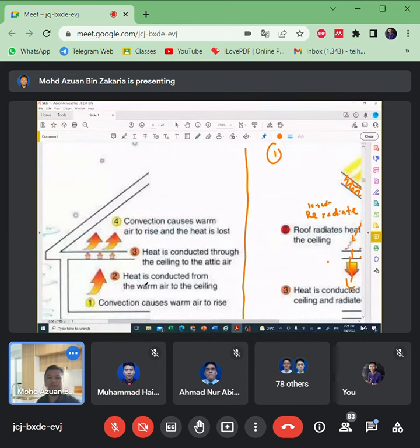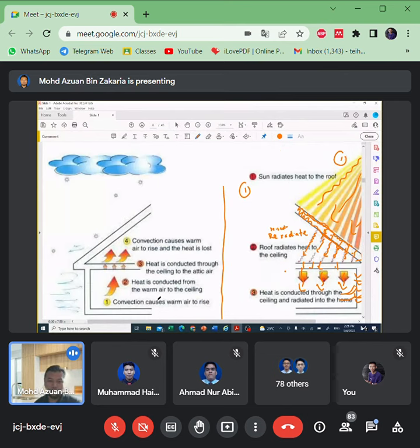Next is how about nighttime? So at nighttime, the outdoor condition is already cold. So what happens is, for example, around 7 to 8 p.m., outdoors goes from sunny to dark, and then what happens? The building structure is still hot, right? But when outside is cold, the heat will release to the cold area, right? Heat always finds its way to a colder area.